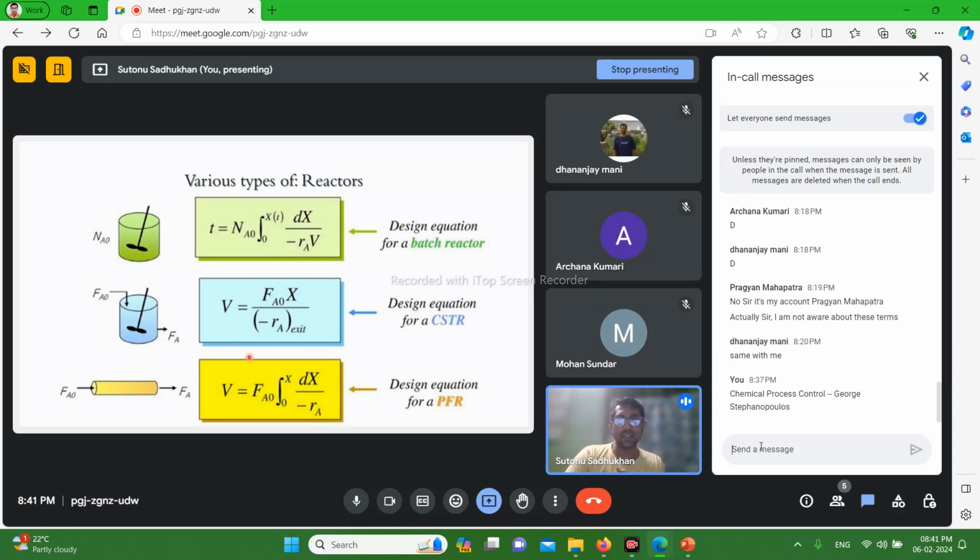But in the effluent treatment case, there may not be any online meters present. Maybe they are taking the samples, testing in the lab, and plotting the data that way. Or maybe shift wise, three or four times a day, they take the sample. As per my understanding, I have also worked in companies, and this is what they were doing, and based on that, they were increasing or decreasing the dosing.